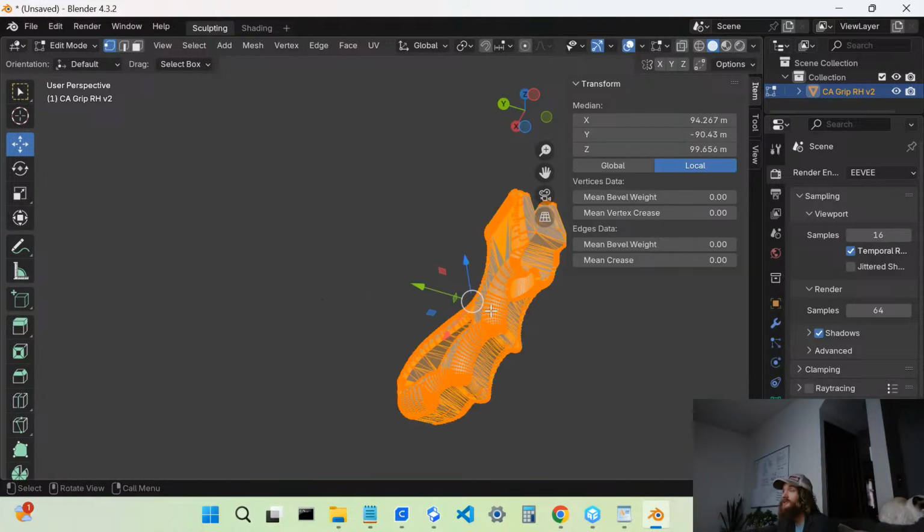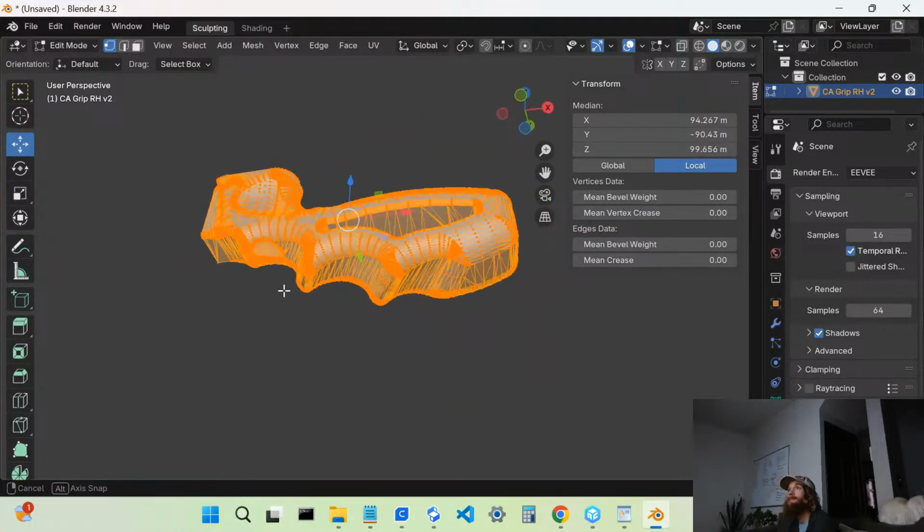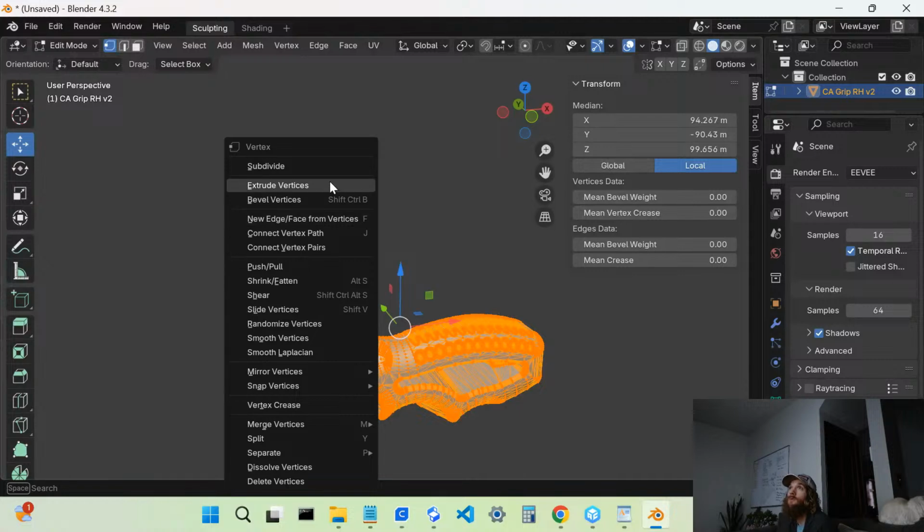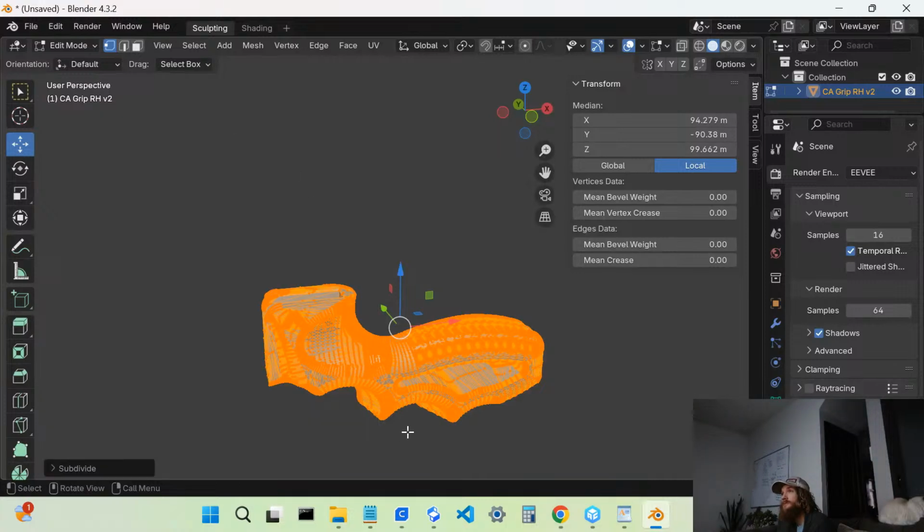Yes, just by hitting just A, not Control A, just A. Okay, so just the letter A on the keyboard, and we are going to right mouse click, and then we are going to select at the very top. I was down here thinking it was alphabetical order or something, but at the very top, you will find this, subdivide. This is going to double our data points, okay?